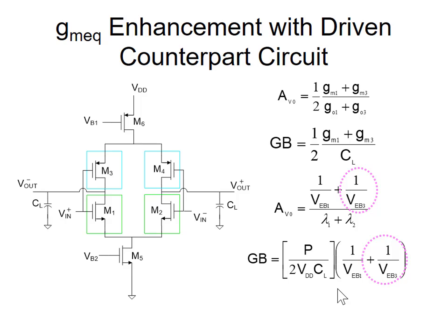Make sense? So both the voltage gain and the gain bandwidth product have improved, and they improved very much. Maybe about doubled, if we make the excess bias of both of them the same. It's not the windfall we got with going to the cascode structures. It's not the windfall in the gain, but recall none of our structures improve the gain bandwidth product. This structure improves the gain bandwidth product too. It's a factor of 2.